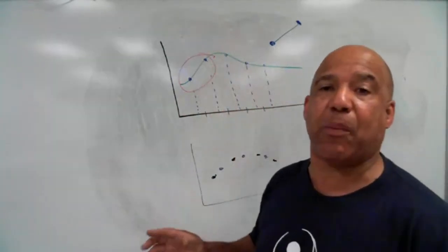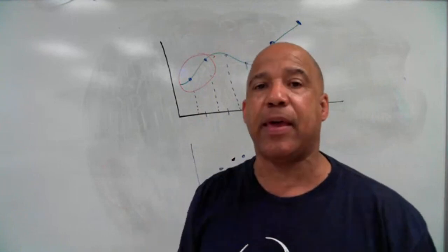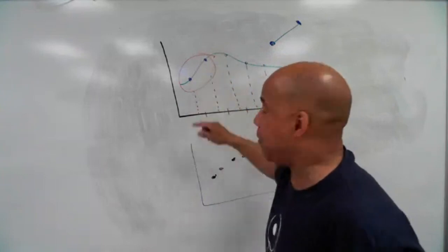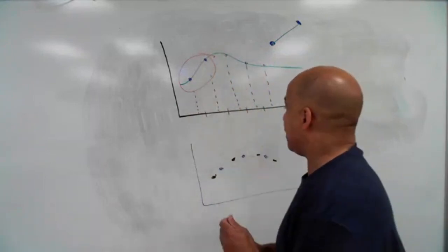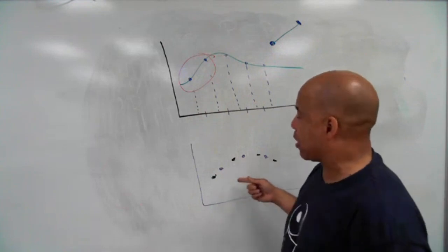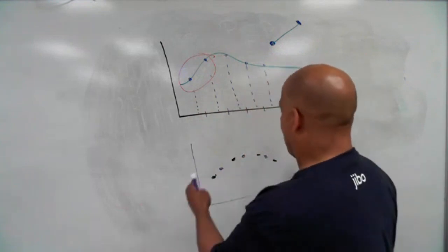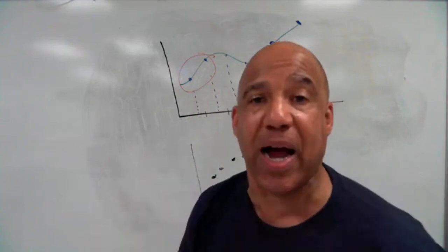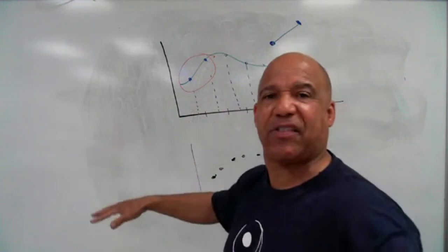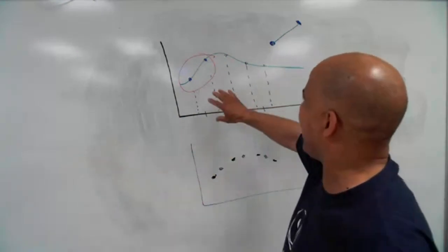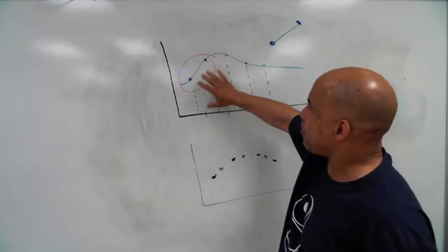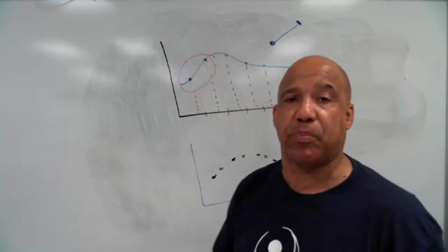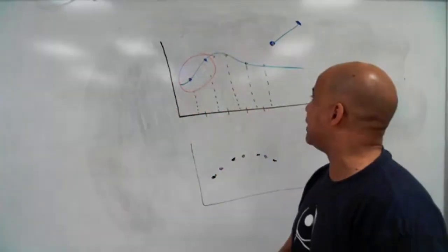The term I've been avoiding is resolution. The more you sample the analog signal, the higher the resolution. The higher the resolution, the more codes I'm going to need to store it, and if I want to move it from one part of the computer or network to another, it's going to take more time. So it's a trade-off. Usually you want a healthy balance between the resolution and how much information you're throwing away. So that term resolution is important: how many times do we sample the signal?